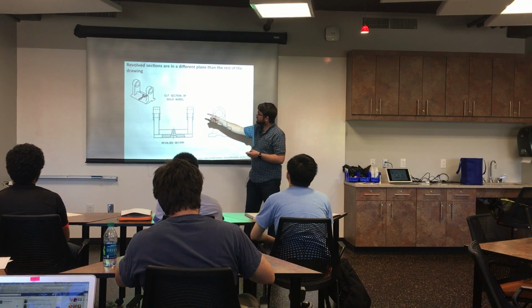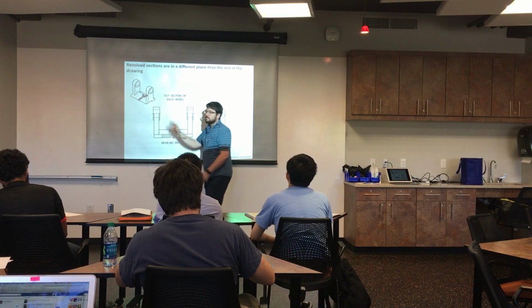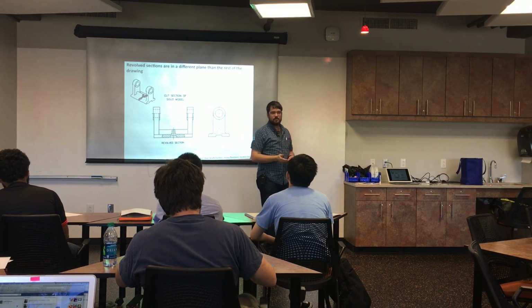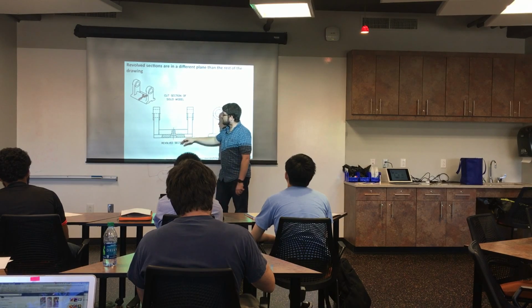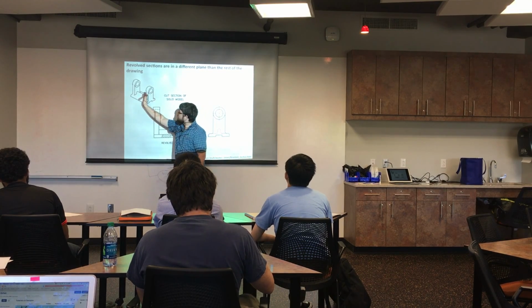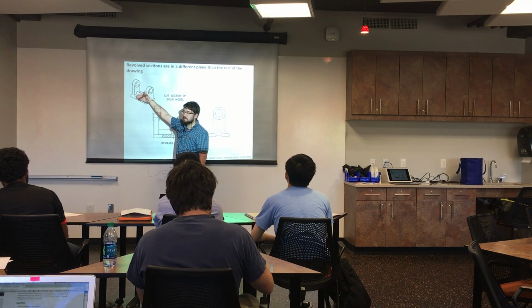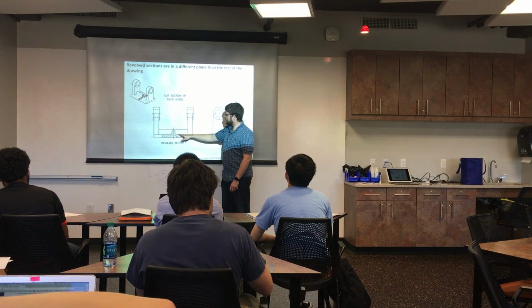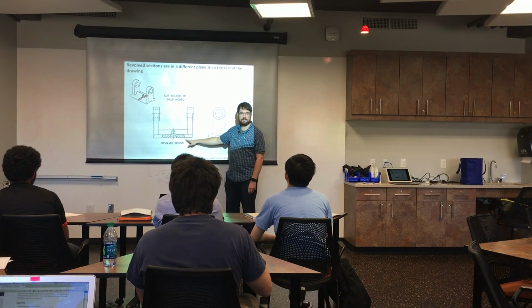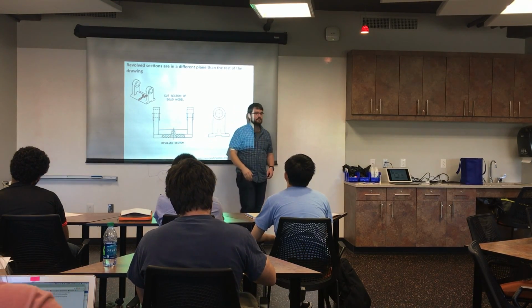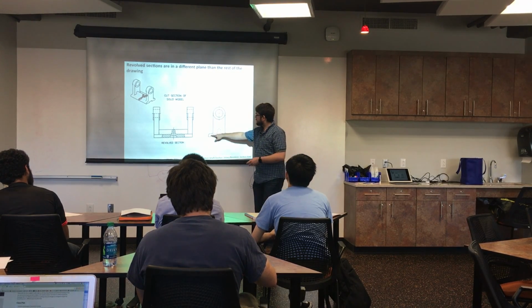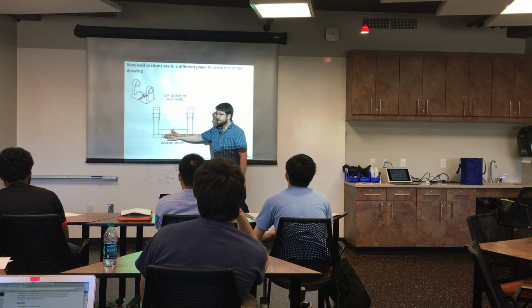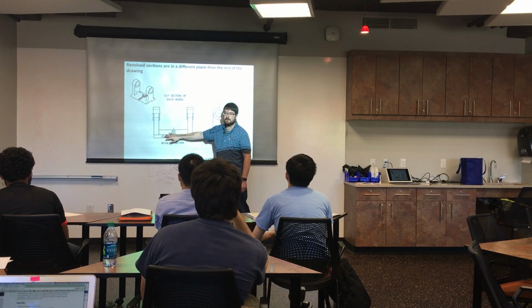Well, you could do like this and then break out a section, but you don't have to. You can use what's called a revolved section, which this would be the side view of the part, and then we take this, rotate it so it's in the plane of our view, and that's the revolved section, because the information that we're getting from the side view isn't very useful, and there's a lot of redundant visual detail there. So again, this will be the section. We rotate it into the plane of the view that we want to put it in and draw it on.